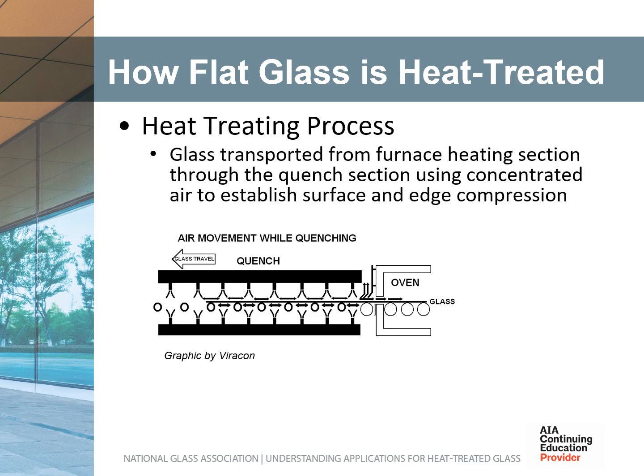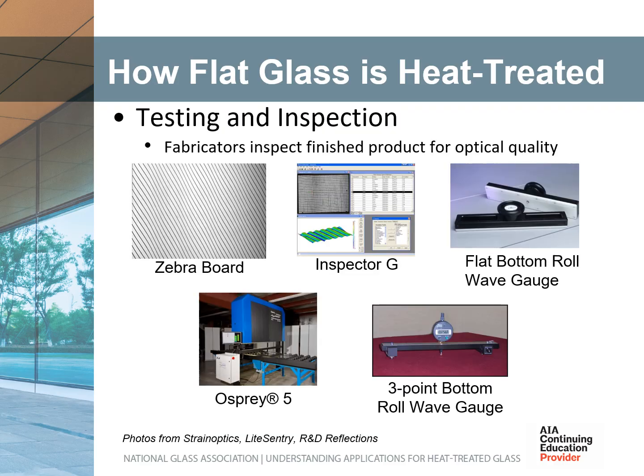After the glass has gone through the washer and is dried, it's ready to enter the oven or furnace to be heated before entering the cooling or quenching phase, which locks the surface of the glass in a state of high compression. Quality control of heat-treated glass is critically important in order to ensure compliance with industry standards, as well as the requirements of specifiers and end users.